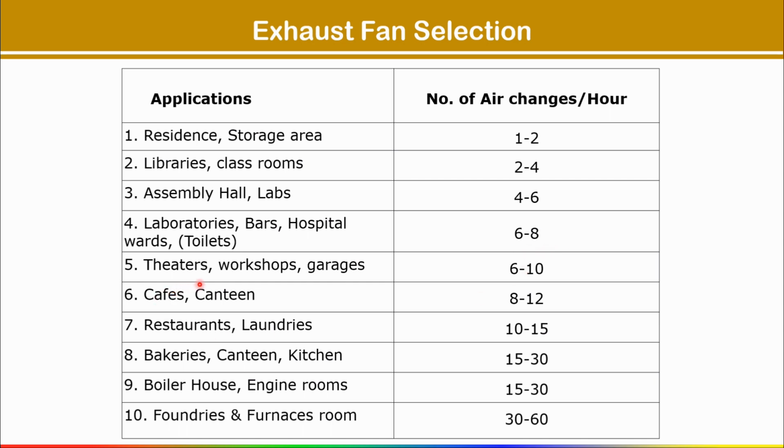If you have installed this fan in theaters, workshop, garage, so for that see 6 to 10. Canteen 8 to 12. Restaurant, laundries 10 to 15 times you have to change the air in 1 hour. So based on this application you will get the ACPH value.